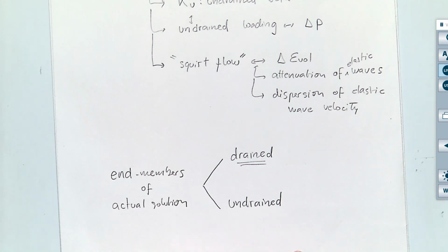For example, if you have a hydraulic fracture propagating through a medium, and if the medium is very tight, as many shales, when you apply a strain next to the hydraulic fracture, the fluid may not have the time to escape out of the pore right away. That's going to depend on permeability, and it's going to depend on a lot of things. And how long it takes to get there, that's something that we're going to see. We don't know that a priori.